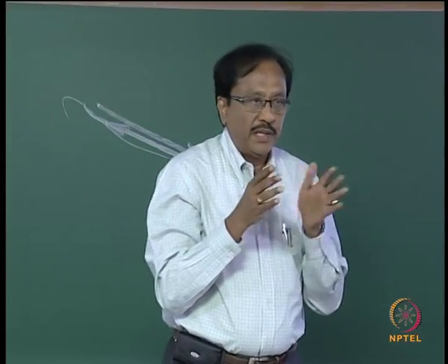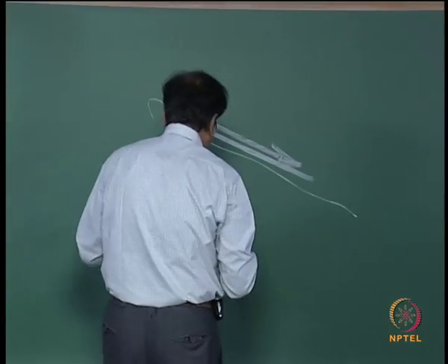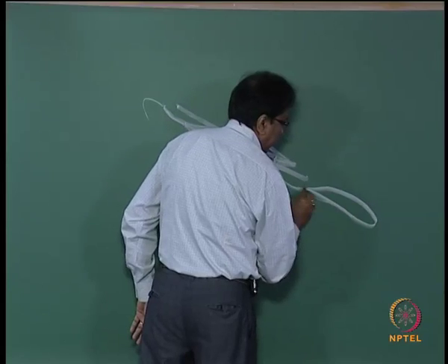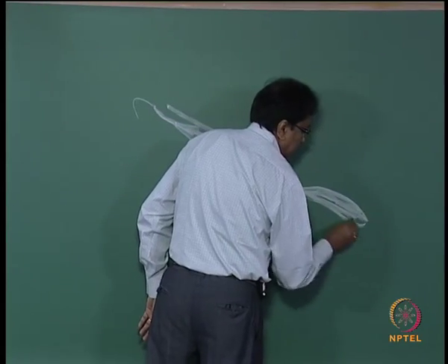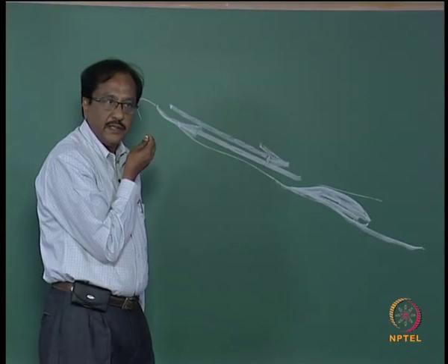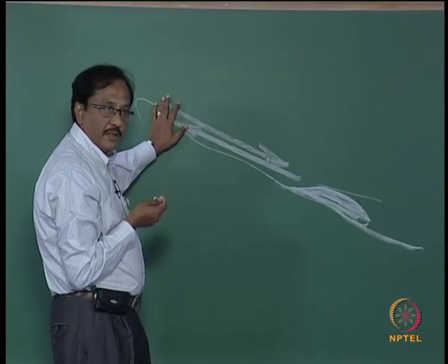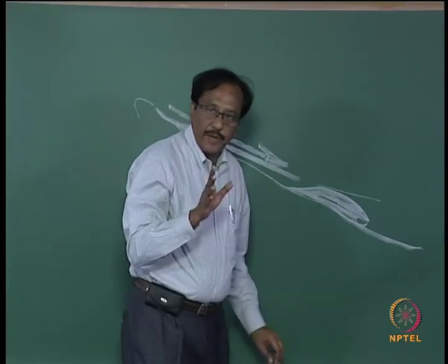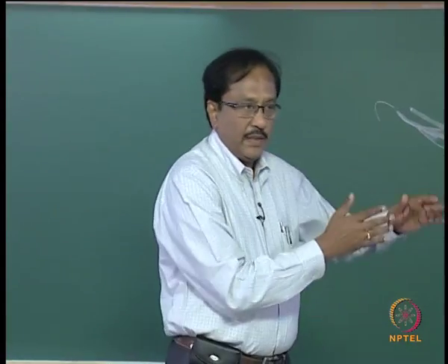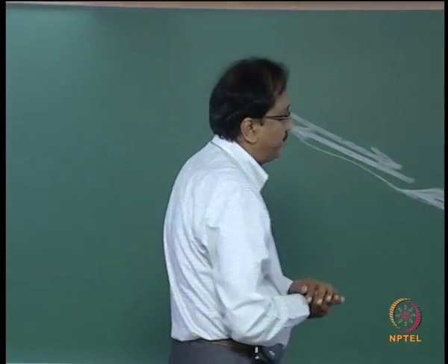Even if you see some kind of erosion taking place, this will remove the sand, and then probably this sand will settle something like a bar, and then again this bar will be removed during low tide, and this sand will again redeposit. So this is one kind of problem which you need to have in mind, whether it is a short term erosion or a perennial erosion.